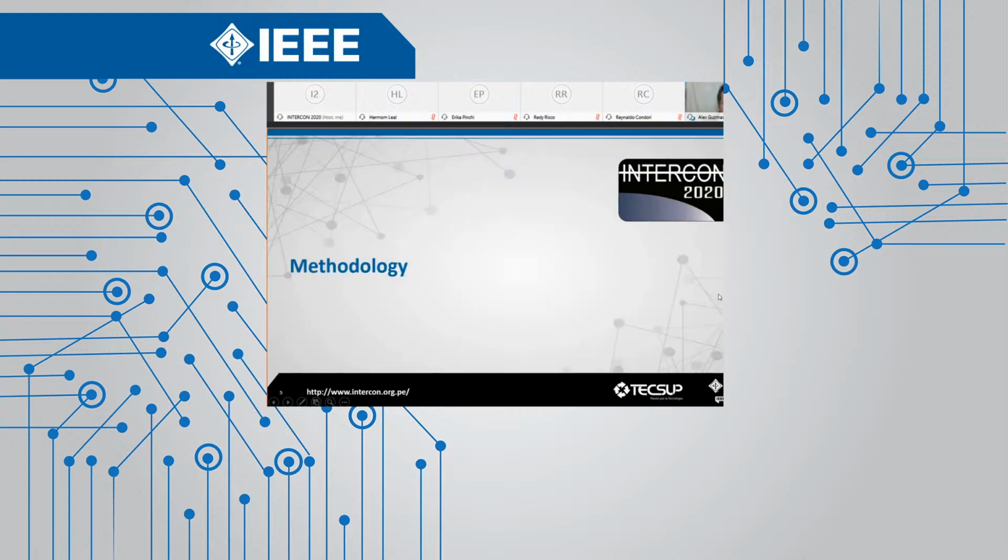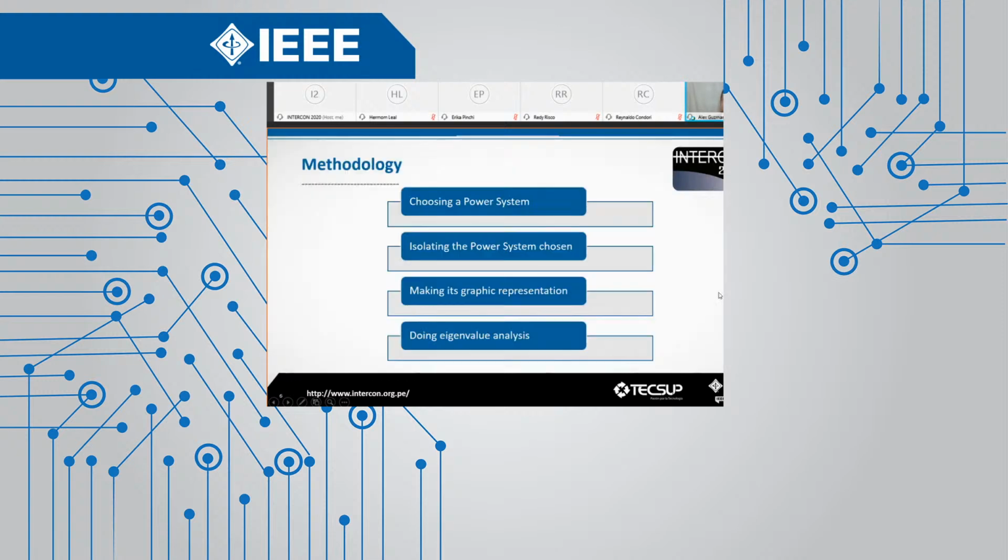The methodology. Well, the first step is to choose the power system. In our case, it was Arequipa's power system. But how did I get its data? Well, COES's website provides us with the entire SEIN data. However, Arequipa's power system is a small part of the National Interconnected System, or SEIN. So Arequipa's power system had to be isolated using an external grid and equivalent loads.